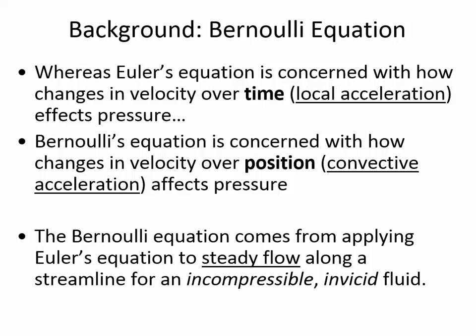So either a fluid is going to be relatively incompressible, meaning that it's probably a liquid, or it's going to have a very low viscosity, meaning that it's a gas. But it's not going to satisfy both of those. And so there's no perfect fluid for which Bernoulli's equation describes things exactly. But if we apply Bernoulli's equation in a smart way, then it can give us very useful results.